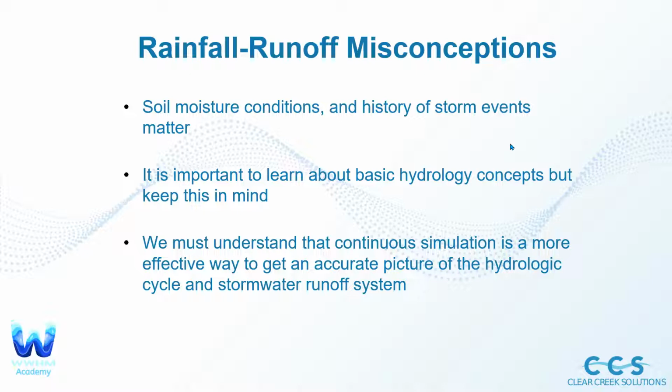So it's not enough just to look at one stormwater event and determine that's how much runoff we get when we have this event. It's much more complicated than that, because we're looking at back-to-back storm events and the soil conditions before that event occurs affecting the amount of runoff. And we need to be able to measure that from one time step to another.